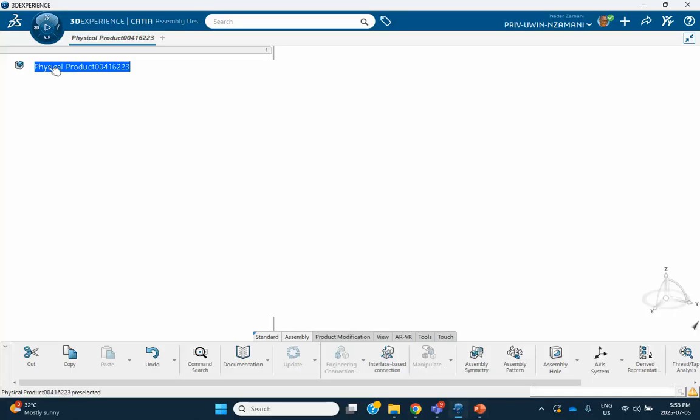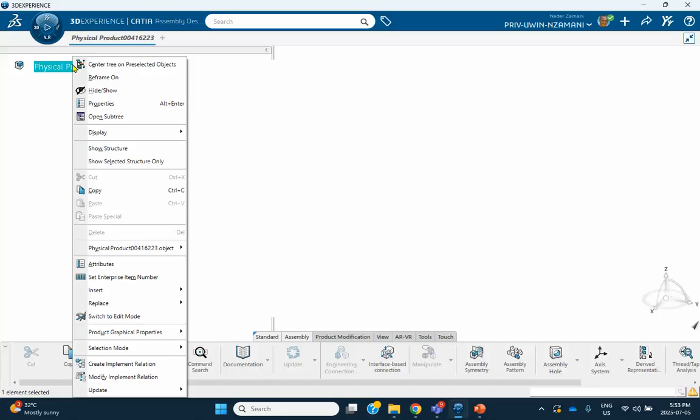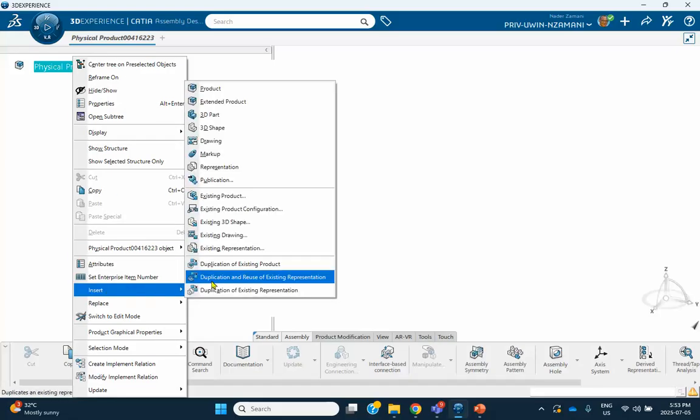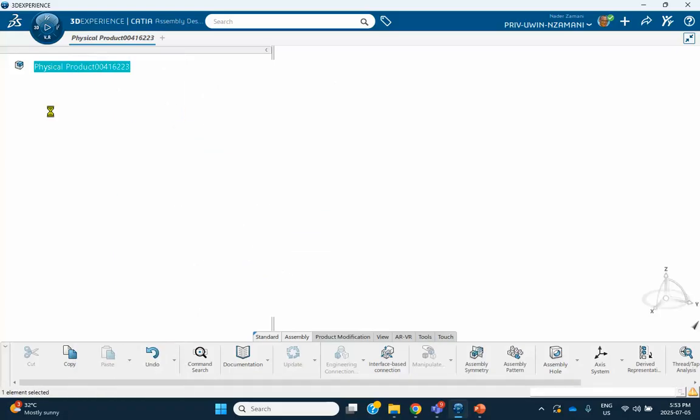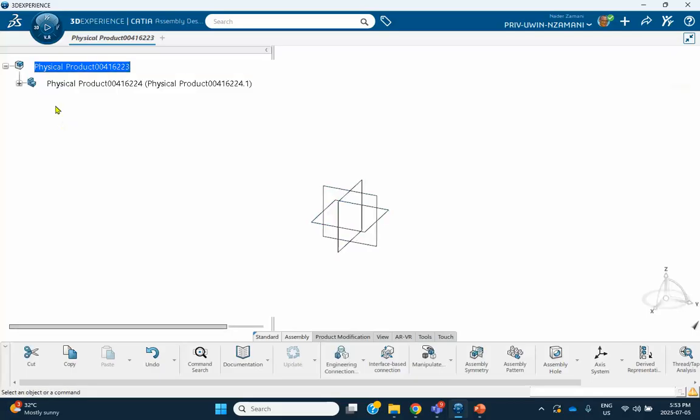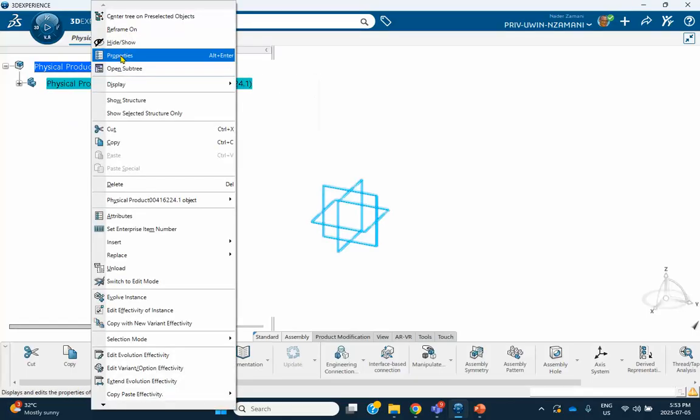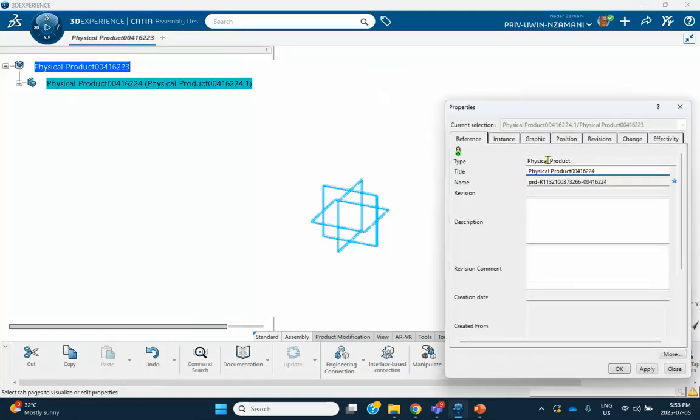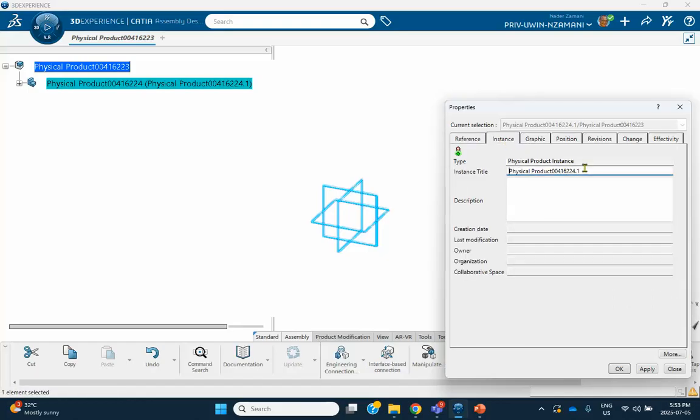Let me insert my first part. Insert 3D part. There's going to be only one part, and that's going to be that disk. Okay. Let me call this properties. Let me call it disk. And here's the instance, also disk. Okay, let's go ahead and make it.